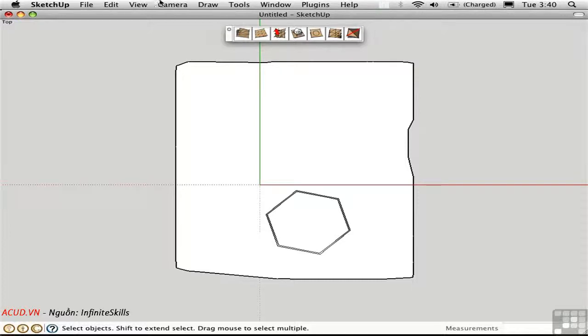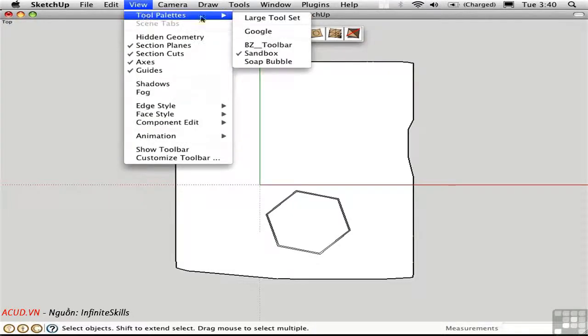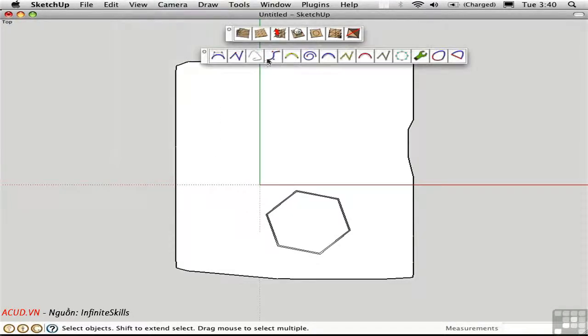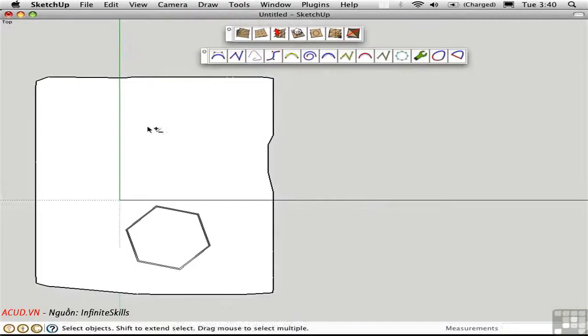I'd like to create a curved path, so I'm going to use the Bezier spline toolbox for that. Now I'll use a classic Bezier curve. I want to be careful that I don't actually snap it to the landscape itself, thereby making a three-dimensional curve. Instead, I want to be sure that I have a two-dimensional curve so that I can make a face.